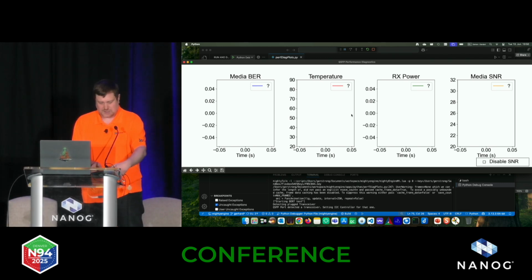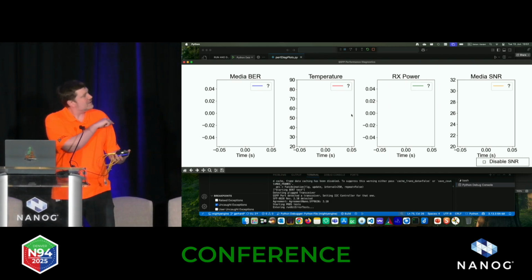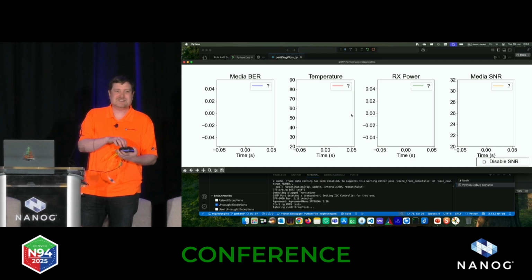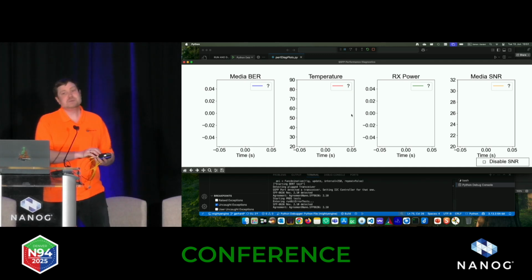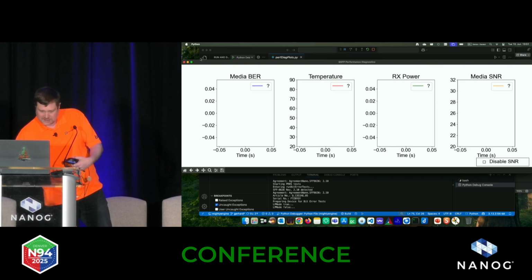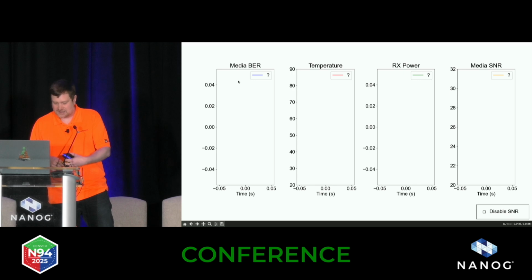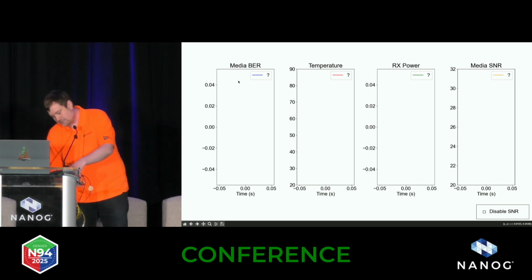Yep. It takes a little bit to boot. I mean, it has to generate the PRBS on the DSP. Since it's almost like a small computer, it takes a little bit of time. But as you can see, it's doing its thing. Let me go into full screen. Yeah, you can see it. And wait a bit. When it is ready, it will start showing our bit error rate.